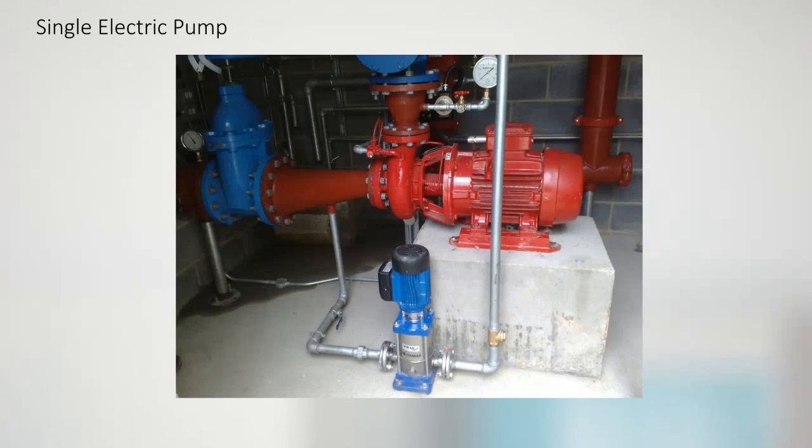your technician or your engineer that the pumps are running, because the last thing you want is for it to kick in on a Friday night, and then when you get there on a Monday, it's still going, because these pumps will keep going until they blow up. Especially with diesel pumps, they are known to go on fire. But if they have kicked in and they're not meant to, you really need to know about it.